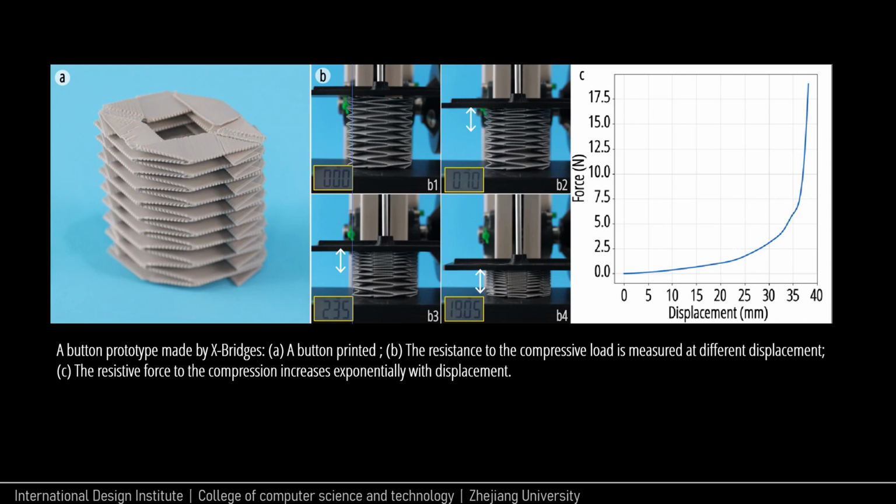Rather than regular even extrusion, we modified the G-code file to increase the extrusion flow linearly from 80% to 160%, which gives the button a resistance gradient on the layer for every segment.